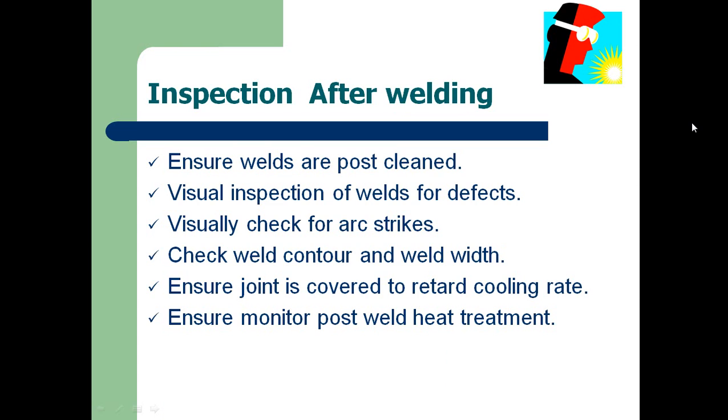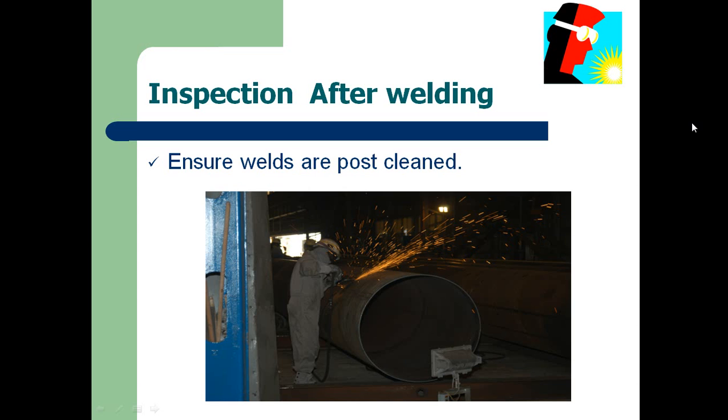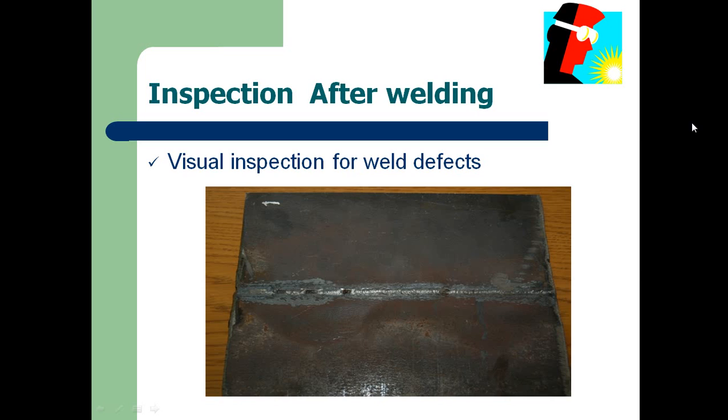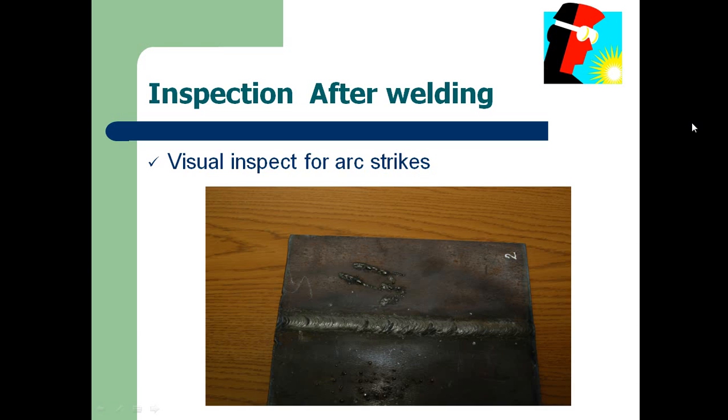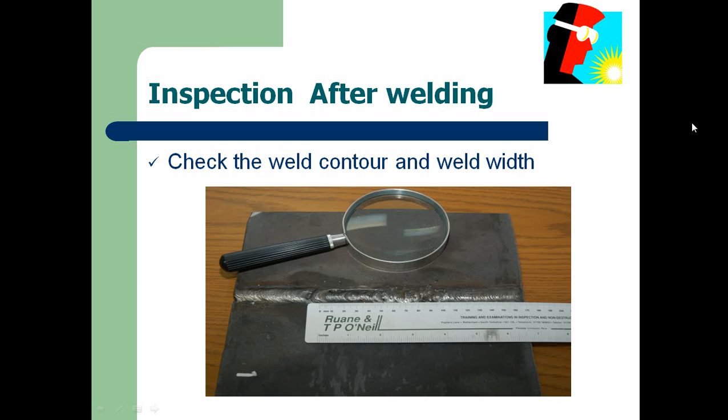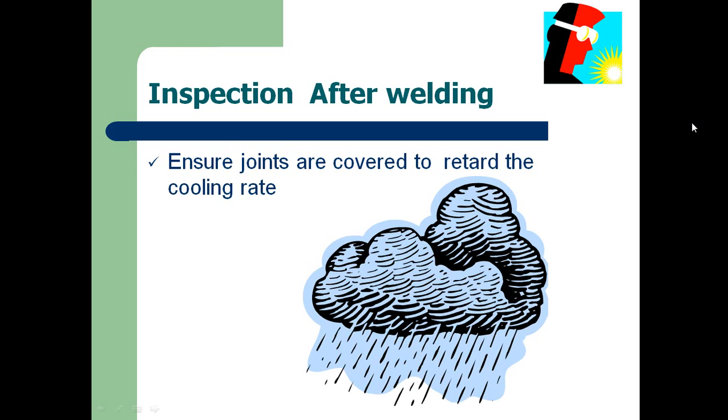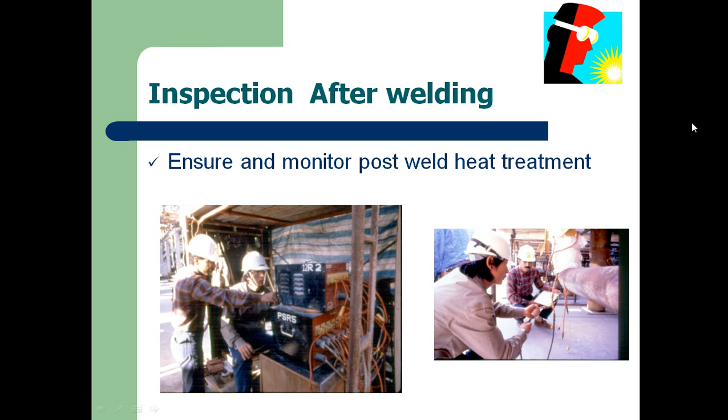Here after weld, these are the tasks for the inspection itself. To check the weld visually, to check the arc strikes, to ensure if there is any heat treatment required. It depends on the thickness of the weld itself.